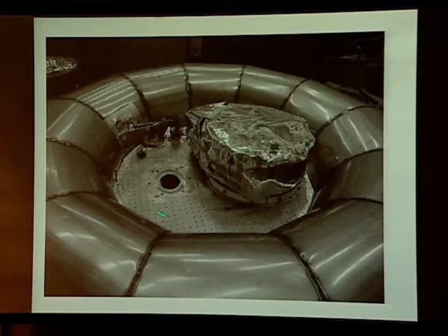You can also see a large number of pinholes. This is where cold helium gas flows out of these little pinholes and keeps the ambient atmosphere from freezing onto this 2.7 Kelvin surface. We have photos and video camera from flight, which unfortunately don't show up very well on a computer screen, but you can see from that there is a little bit of condensation from nitrogen on the edge here in flight, but it doesn't build up with nitrogen ice on the surface during flight because of that outflow of helium gas.